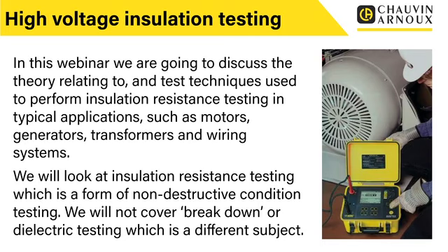That term non-destructive is very, very important. We're not trying to prove what voltage we can use to break this equipment, or what voltage we can use to get the insulation to flash over under surge conditions and things like this. What we're doing is using these high test voltages, this insulation resistance test, to non-destructively test and monitor the condition of insulation. So that's where this differs from something like flash testing or dielectric strength testing. We're not looking to break it down. We're not looking to put this insulation under so much stress that it may get damaged. We're looking to do non-destructive testing so that it's repetitive and we can continually monitor and compare the conditions over time.